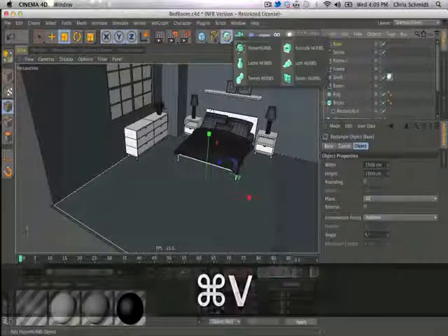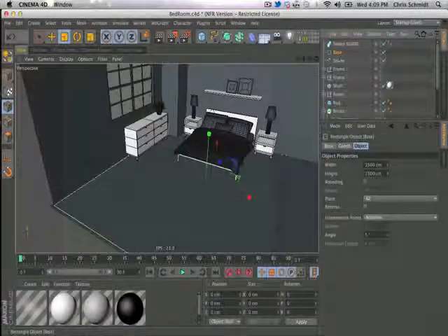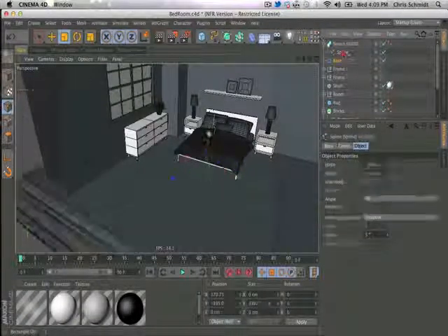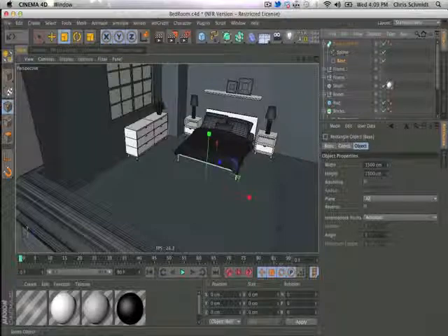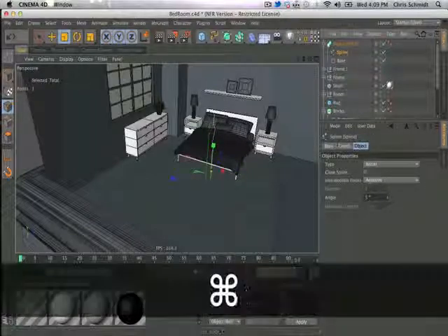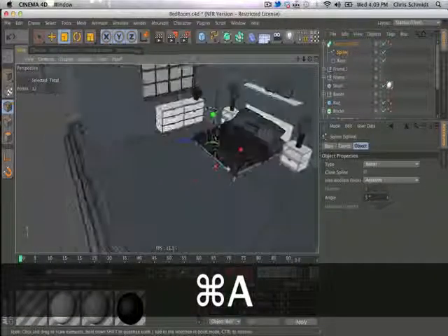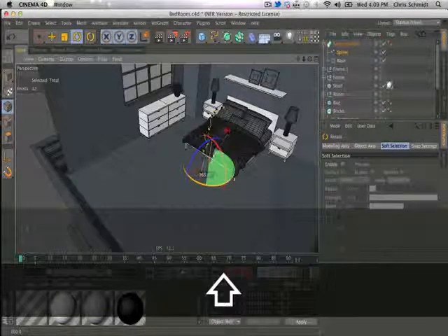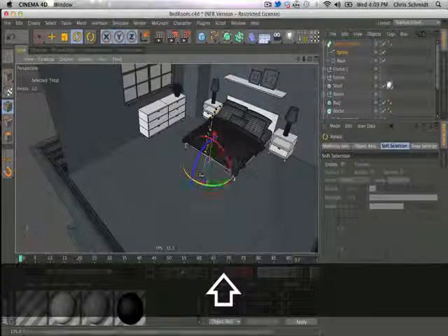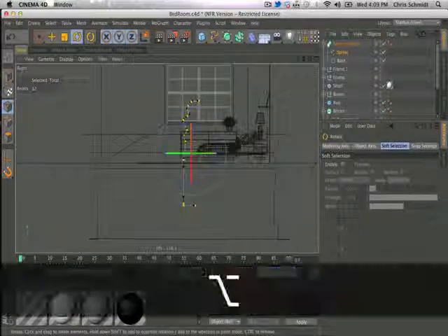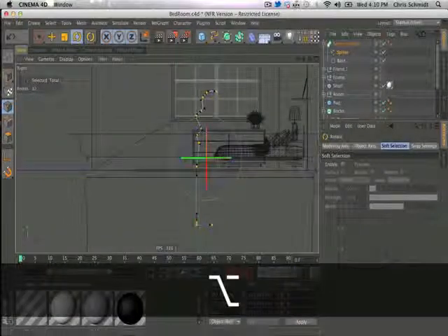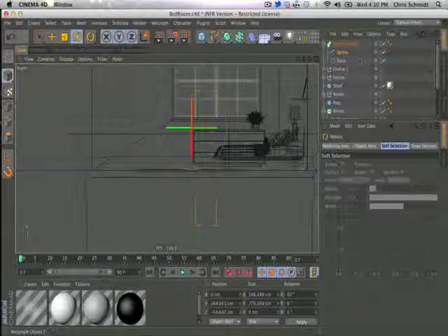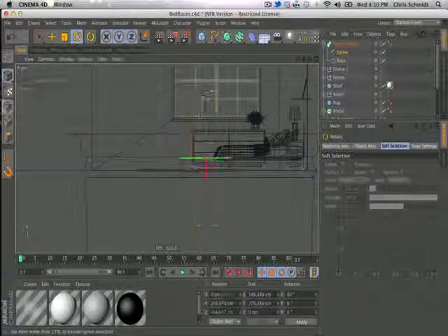So now we can take that, and we get this base, and paste that up at the top. And now we can go to sweep and put this in first, put the base in under it, and it should be sweeping that around. Of course, I did it backwards, because I always do. So we can select this entire trim, and I'm going to rotate it 180 degrees, so it's actually on the inside. And you got to make sure it's kind of off from the axis. So let's see where the axis point is of it. See, the axis is here, but it's facing out.